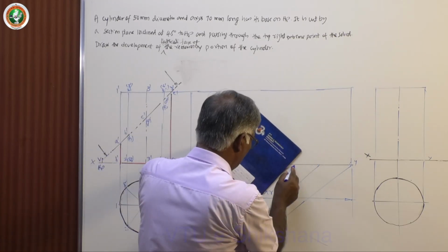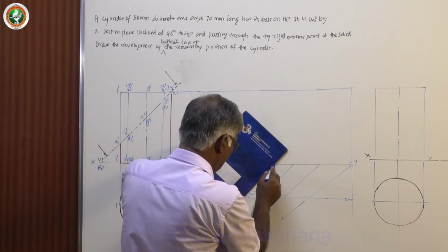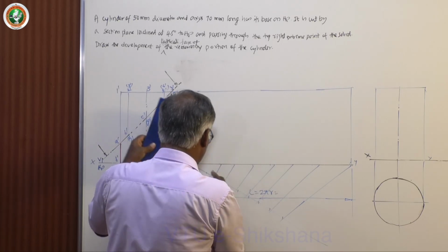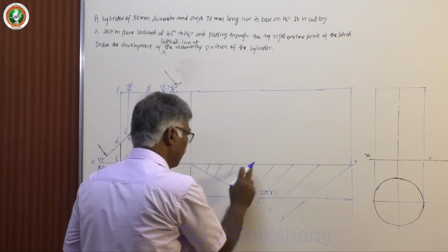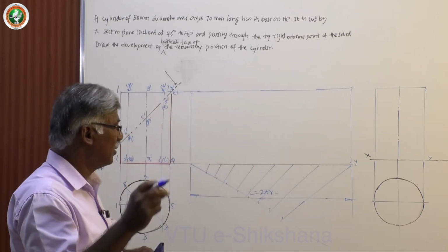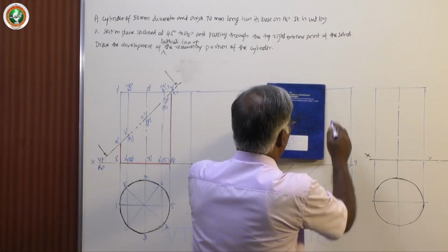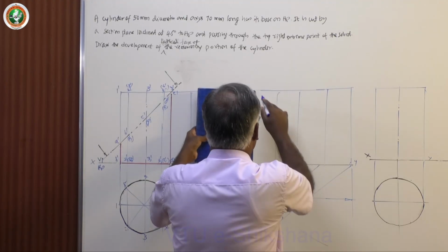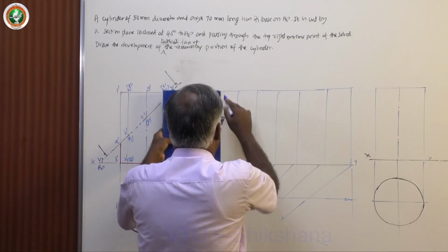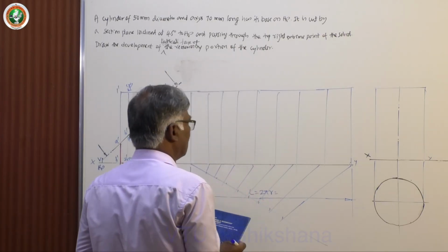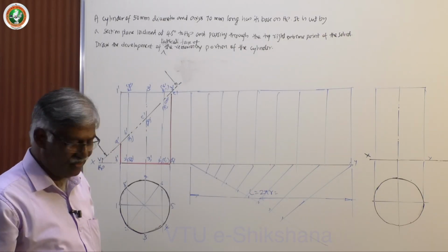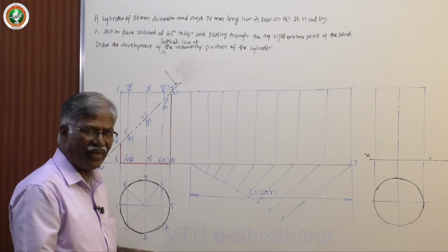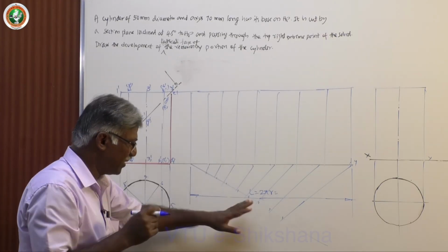Okay. Draw parallels to the first line. So you will get all the time the one which is available like this: 1, 2, 3, 4, 5, 6, 7, 8. Please count, it must not exceed 8 because you are done with this. Now, assume that I am taking equal distances and got the divisions here. So I got little bit changes. Assume that it's all equal. This is the procedure, or you calculate the total divided by 12, approximately you take and do it. But the best method is this.